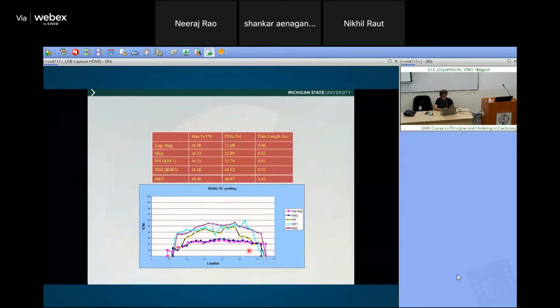And the neural network approach produced something that is very close to the blue signal. We had 2 different types of neural network, and we were able to get much better results. These are actual experimental signals and actual defects from a decommissioned steam generator unit. We were able to pull out the tubes and do a metallographic evaluation.